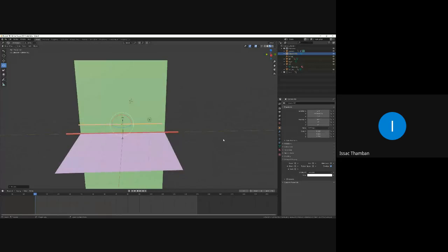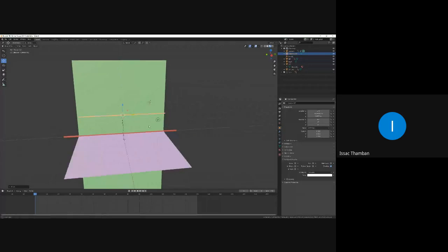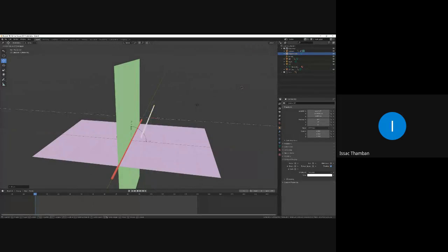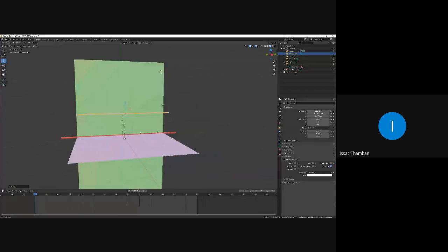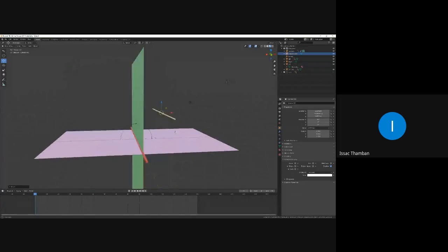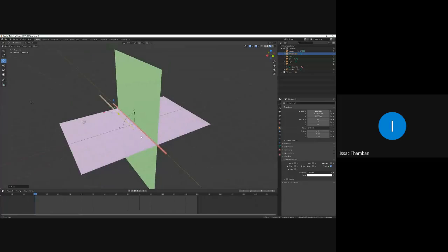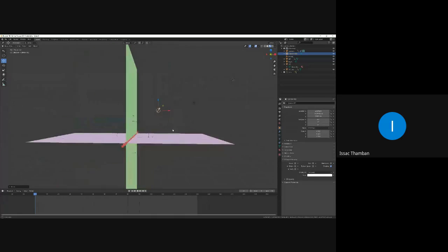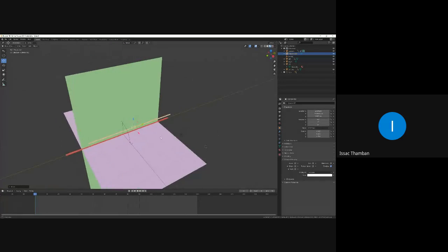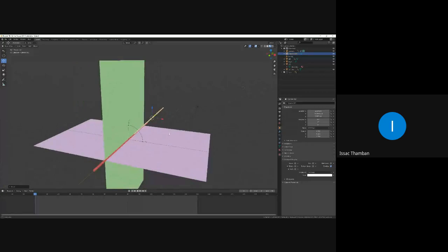So now the line is parallel to HP and VP. What is the specialty of this line? This line will not intersect HP or VP. That means there won't be any horizontal trace or vertical trace.